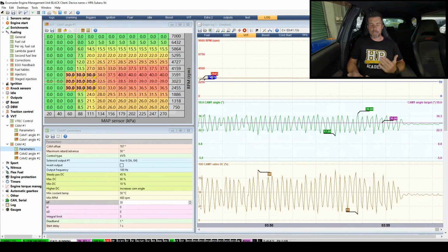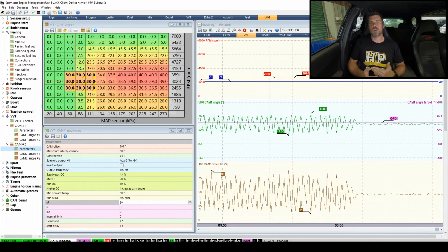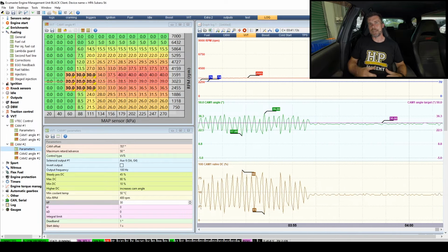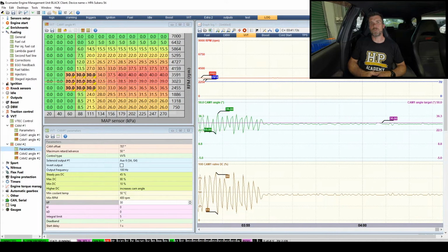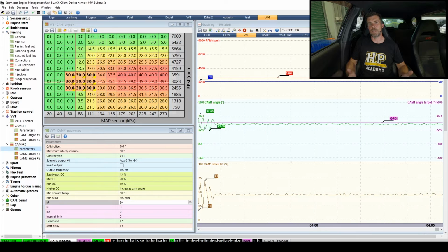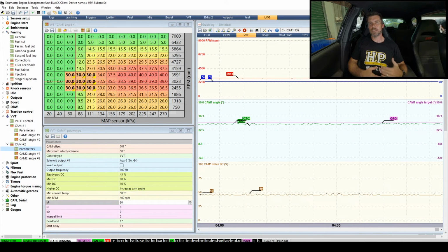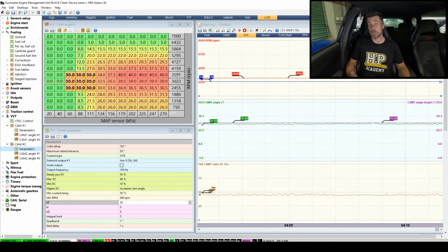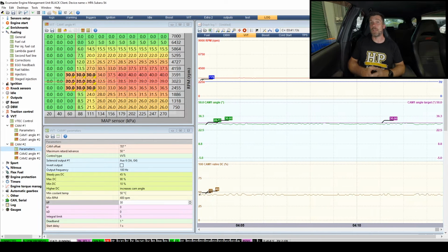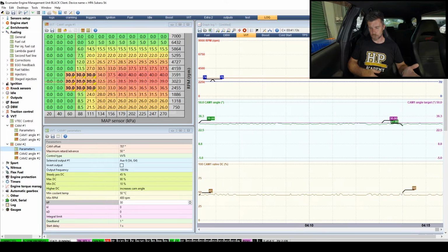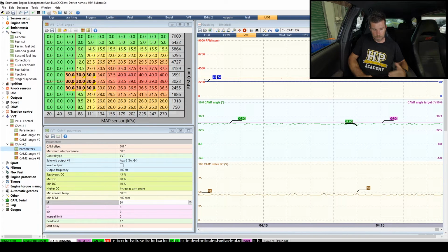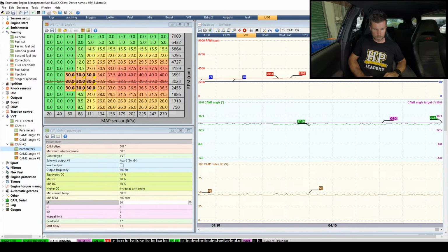So basically, as we've discussed in the body of the course, a good place to start is to make significant changes to your proportional gain. There's no danger of damaging anything here, but we want to find the working range for our particular system. So a good way of doing this is to double our values. That way you'll really quickly creep up on that area where we lose control. So back down to 30, we're going to leave it there for the moment.